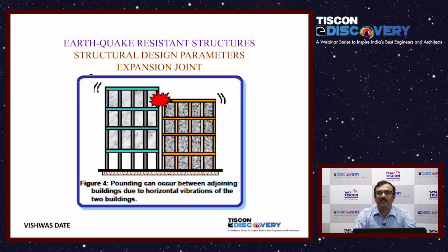What are the issues in terms of design that we need to look at? Let's say we have residential buildings which are long, and that's why we divide them into convenient small buildings. When we divide them, we introduce something called an expansion joint, and the expansion joint needs to be treated carefully. Very importantly, there have been instances where the buildings were too closely spaced and actually collided against each other, causing damage that perhaps would have been avoided if the buildings were slightly more separated. The buildings individually were designed better and could have survived the earthquake better if they had not collided with each other.